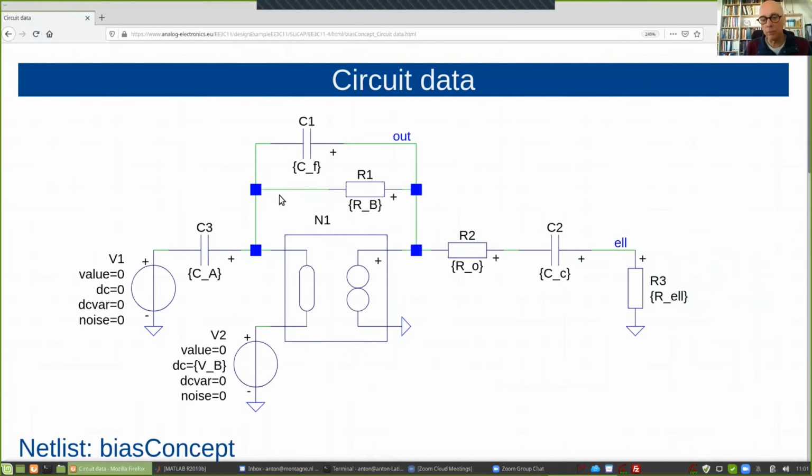It makes DC feedback, so that this will also be for DC 0 volts and no current. And in practice, of course, there will be a controller here, an op-amp here that needs a very small current, and that sets a limit to RB because any current here will make an error.